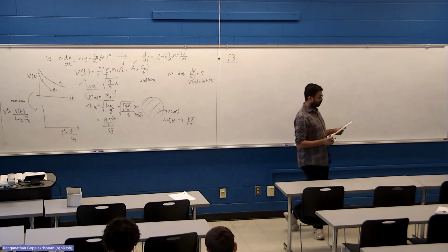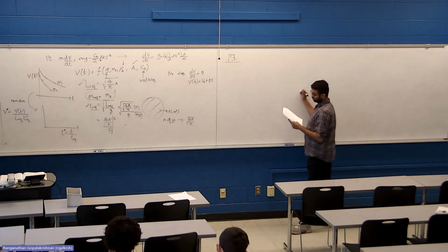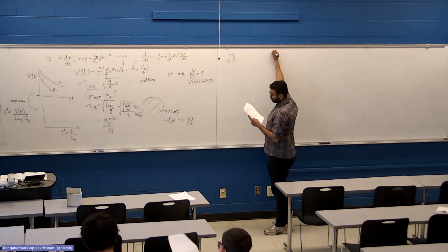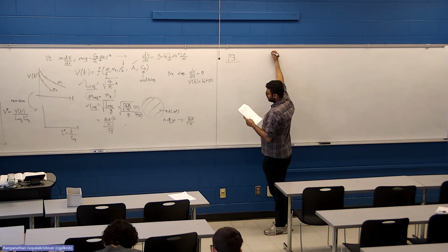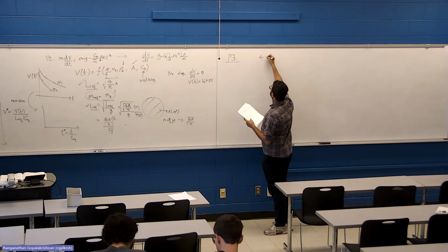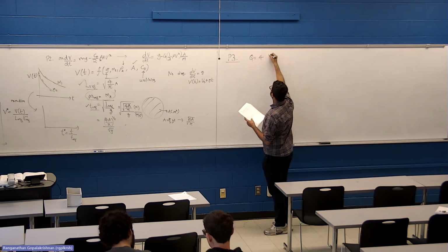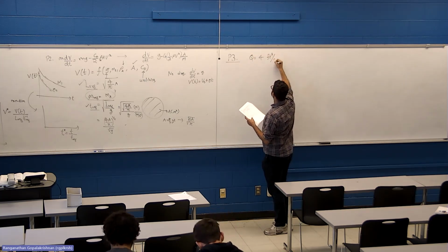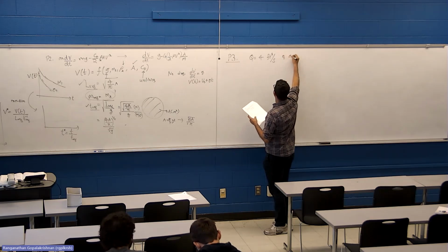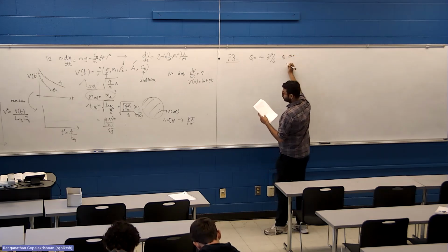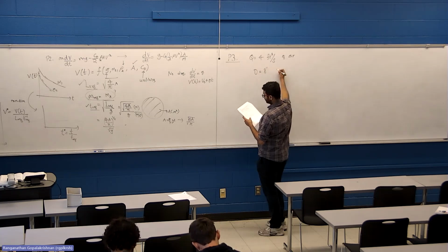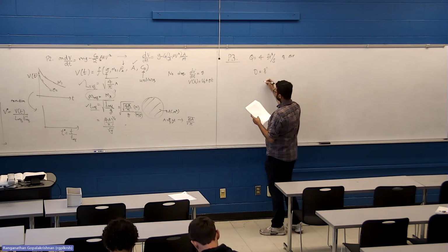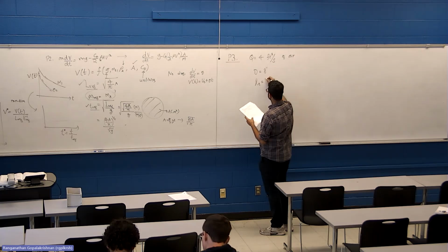Okay. Problem 3, please take a read. I think we did this problem or something similar. To cool a given room, it is necessary to supply Q equal to 4 cubic feet per second of air through a pipe whose diameter is 8 inches. Approximately how long is the entrance length for this pipe?